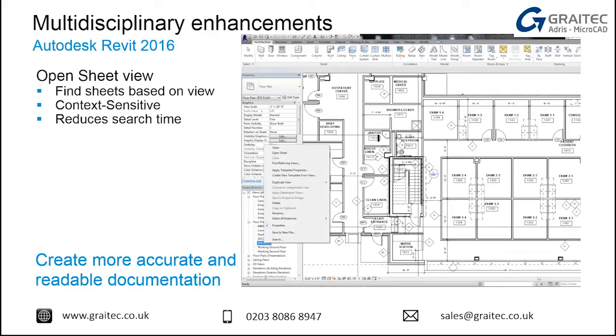All our drawing sheets are stored within our project, but sometimes when you've already placed a view on a sheet, it's a bit awkward to find out which drawing sheet you've placed it on. We can now select a view, right-click, and it will automatically take us to the drawing sheet that drawing is already on. It just reduces search time, particularly if you weren't the person that set that drawing sheet up, and you might not know which sheet it's being applied to.